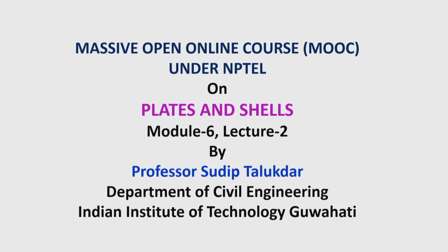You are very much familiar with the buckling of columns in your undergraduate courses, but there is some difference between the buckling of column and the plate that I have told earlier also. When the column buckles, the buckling load of column is the failure load that is taken in design. But in case of plate, we have seen that once the plate buckles, the post buckling strength is also higher. So, another important observation in buckling of plate is that